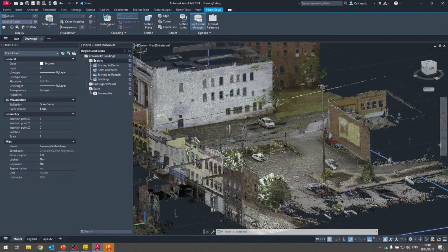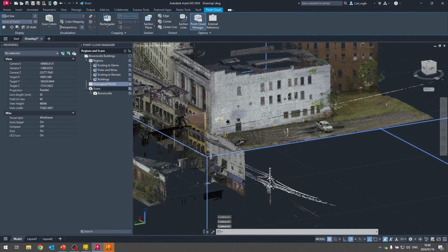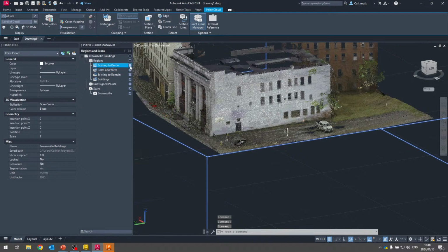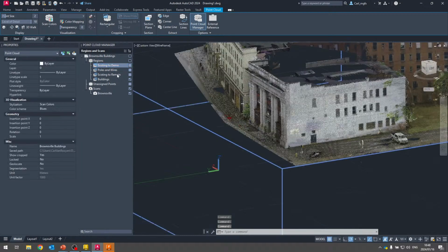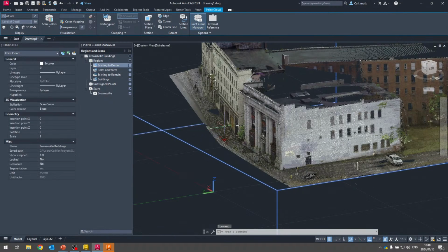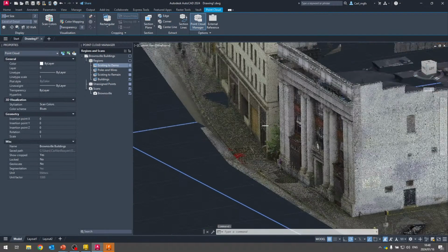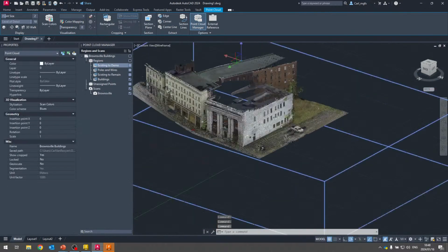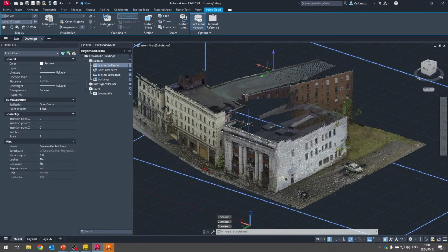to go to the point cloud manager, and you'll see here we have regions and unassigned points. So we can choose to not display the specific points. So if I go existing to remain, poles and wires, existing to demo, they're looking at, in this case, existing to demo and existing to remain, buildings that are being demolished and buildings that should remain. It's a nice easy way in this case to show the contractor this is what you're doing. But for our case, let's say we're a signage company, we have to do some signage on the side of the building. We're able to leave just those buildings within the scan. So you can use that point cloud manager to hide the regions that you don't need. You might be doing multiple project work on multiple buildings in the same area, and so you could hide and show the various buildings that you're working with.